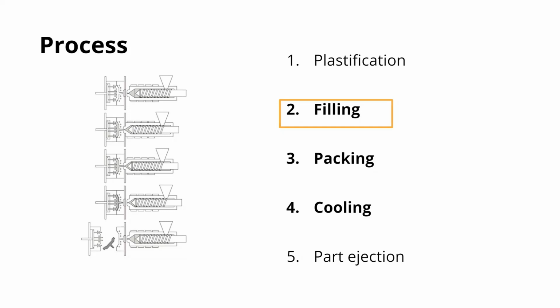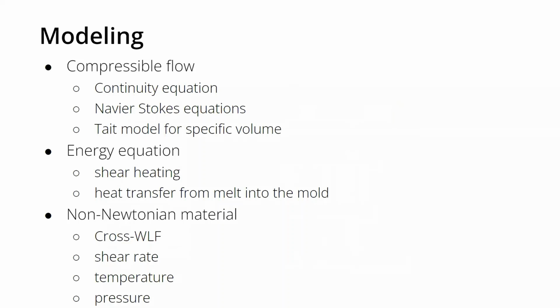Then in the packing stage, additional pressure is applied in order to fill the last parts of the cavity. Then the part is cooled down, and then it is ejected. And I concentrated mostly on the injection part because this is the most challenging part of the process.